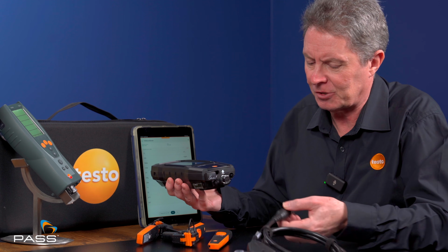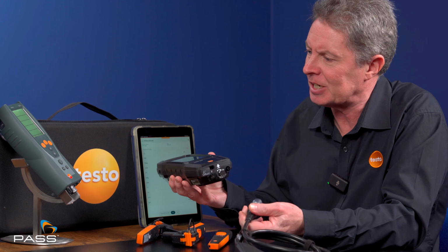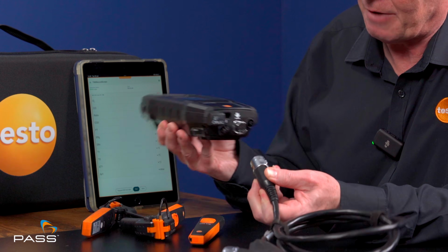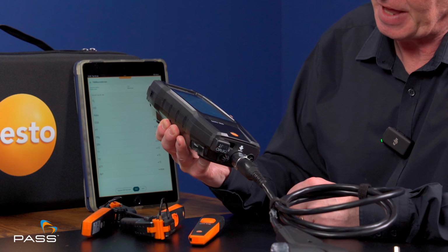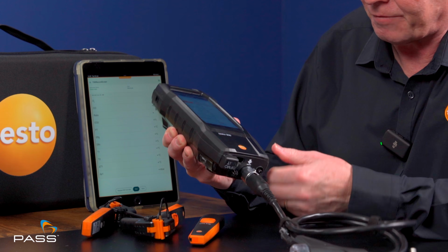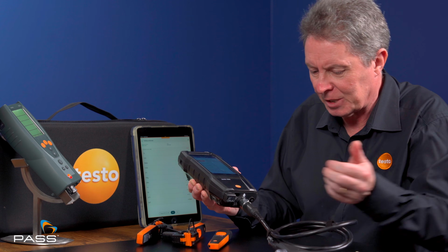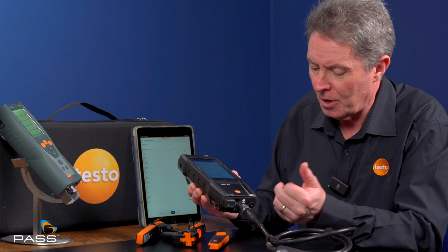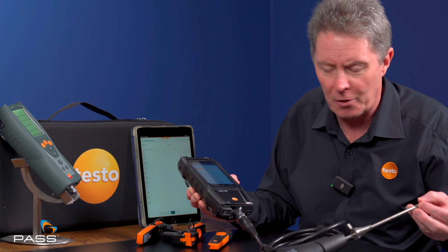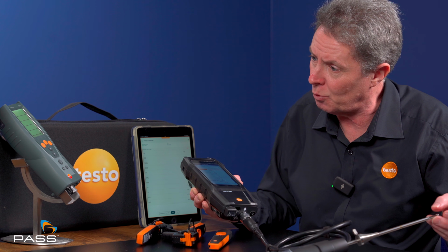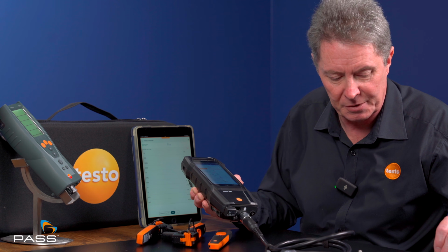We're one of the few manufacturers that's really got a properly engineered solution to the connectivity. What we have on the device is effectively a locking bayonet type connector. You can see that locks on very securely. That's not coming off. It's not a hose that just pushes on. That's bringing down both the gas pathway, but more importantly, that's also bringing down the temperature measurements. So in the flue probe, you have a thermocouple, which is your flue temperature measuring device.